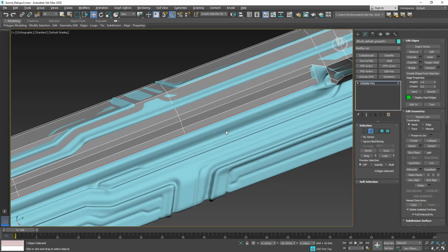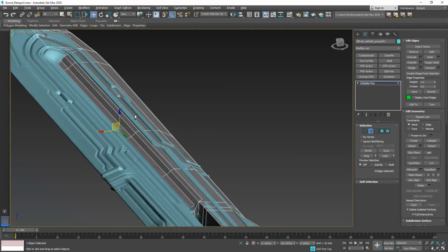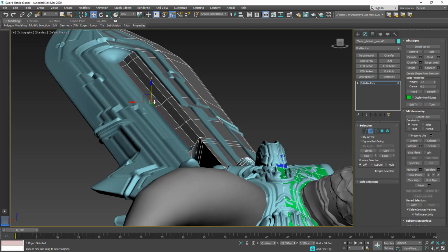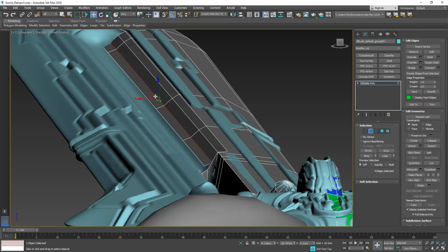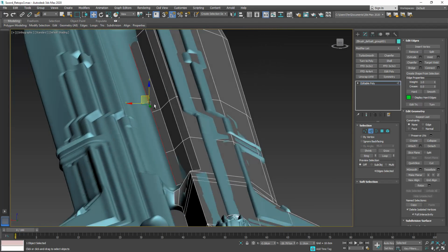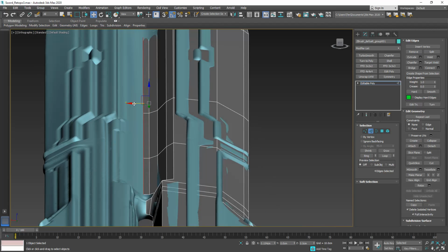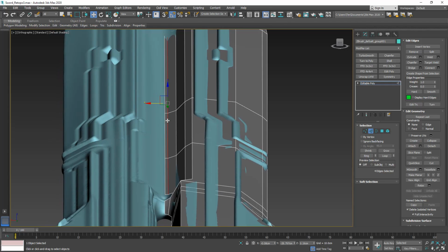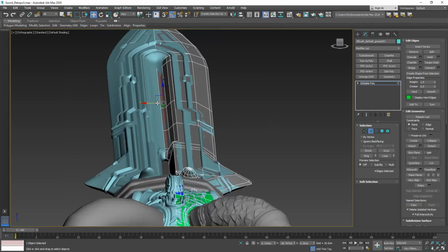So this way we have this curvature there. I'm just gonna go back here to this line and drag it a bit further in there so that we have a bit more of a curvature. Then let's go back on this one. Remember, double clicking an edge will make a whole loop selection for it. So now it looks okay. I'm gonna drag out one more line and align it here on the X-axis. Just click that little button there, the little arrow button.